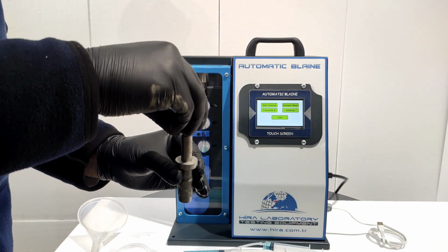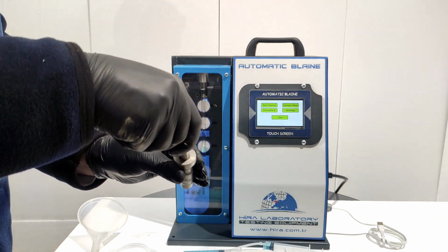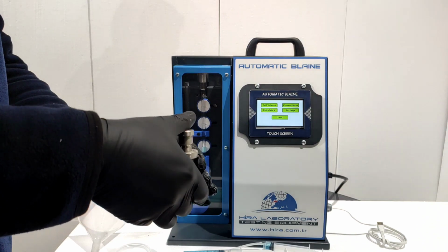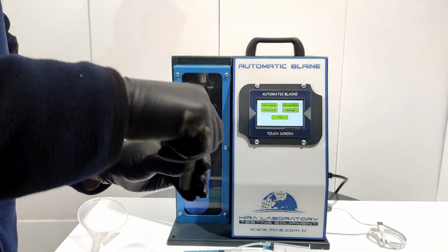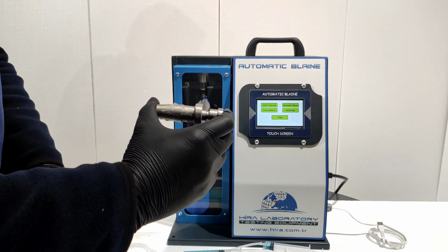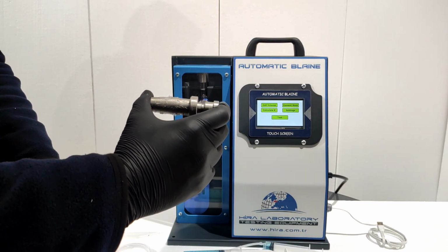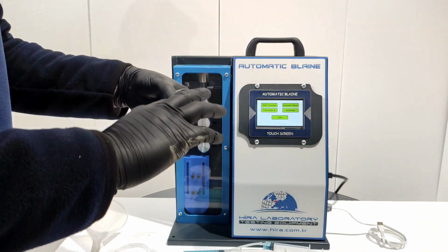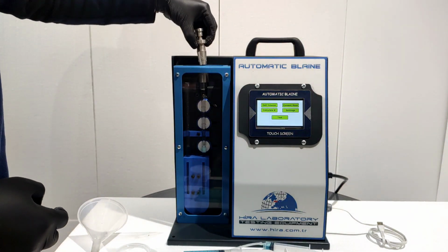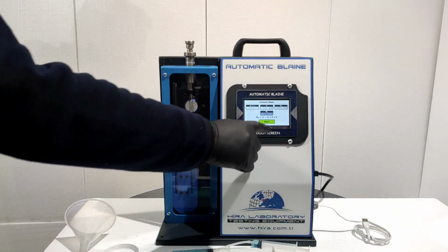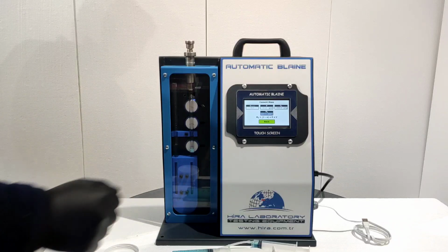To compress the cement cell, press the plunger lightly but firmly onto the seat with the bottom face in contact with the top edge of the cell. Then slowly lift the plunger about 5 mm by turning 90 degrees and press it back onto the cell. The cell now is compressed. Slowly retract the plunger without disturbing the sample cell. Place the lightly oiled cell into the U manometer tube.